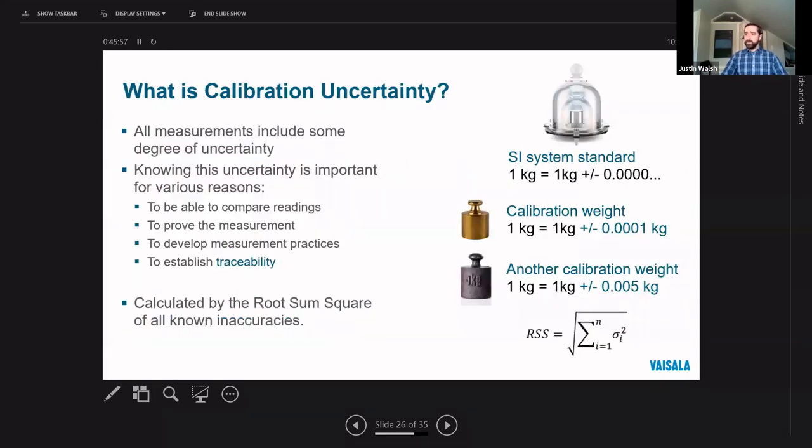Now, every measurement you can take is imperfect in one way or another, and the most accurate instruments will have error if calibrated against a poor reference. This is because of the nature of measurement and because we can't ever really verify if a perfect measurement occurred. The next best thing is to quantify the possible inaccuracies into an uncertainty value. This uncertainty can be summarized as the range of possible values where the actual value could be.